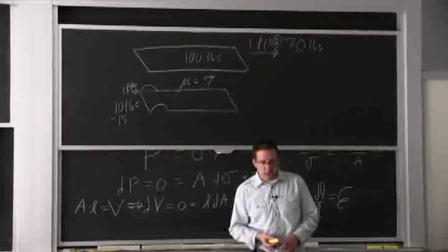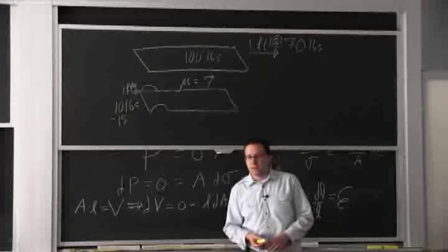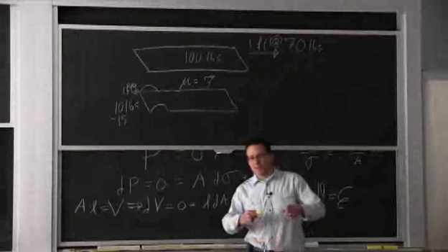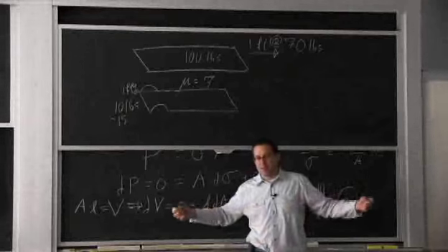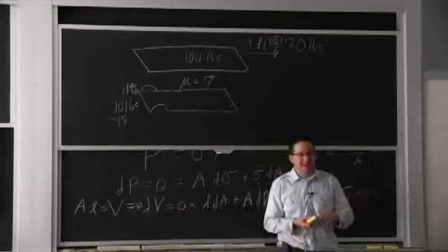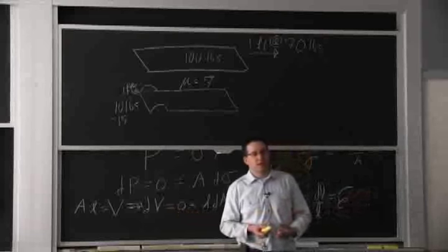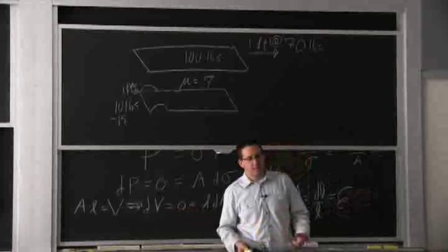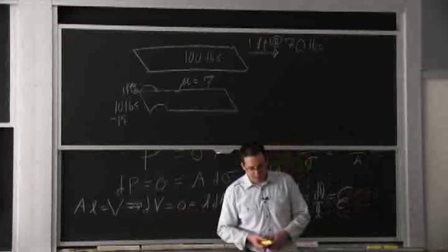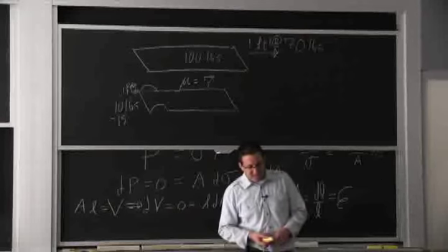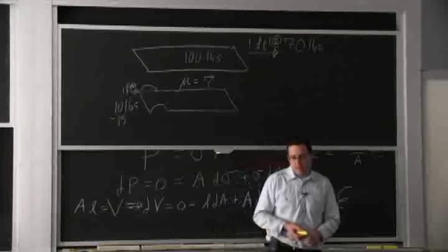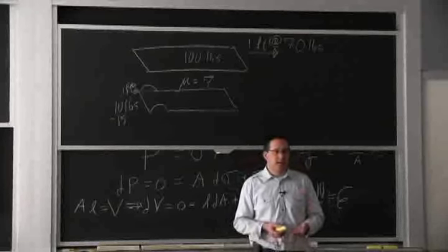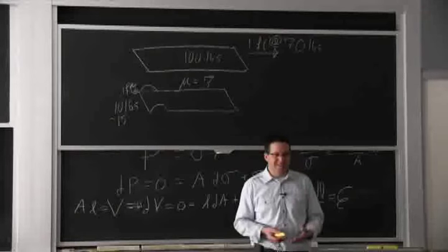We also try to work in compression. The aluminum cans that we're all familiar with normally get drawn in dies to generate strong compression conditions, so you can keep yielding without breaking them. And at the end, for cars and for aluminum cans, there's a strong orientation effect that's created in those grains.